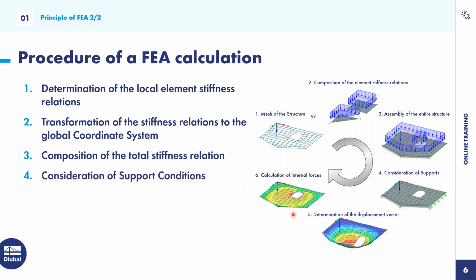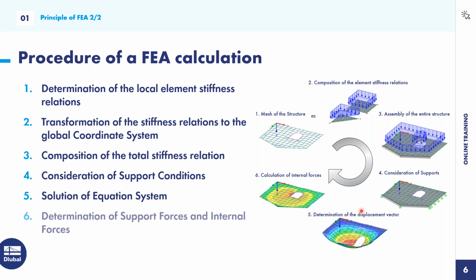Yeah, and then I can determine the displacement vectors. So I solve the equation system, and then I have the possibility to calculate backwards to the internal forces and also to the support forces. Yeah, and this was the basic procedure of an FEA calculation.